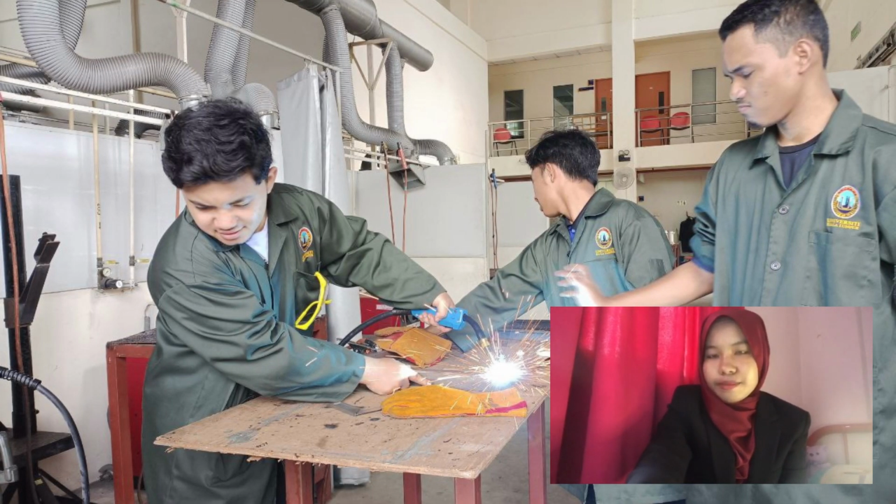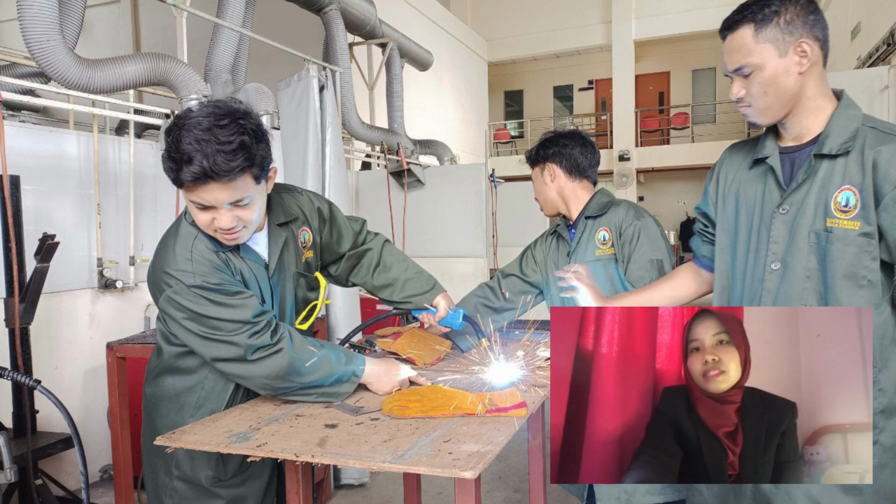Alright, the next step is fabricating. The tools that we use are the GMAW machine, hammer, and welding clamp. The fabricating process should be implemented using GMAW primarily. In this process, the iron parts must be connected. Then use a low base current to maintain the arc, and a high peak current to melt the electrode wire and detach the droplet.